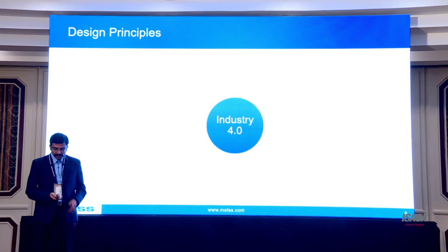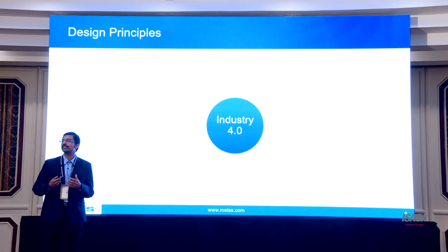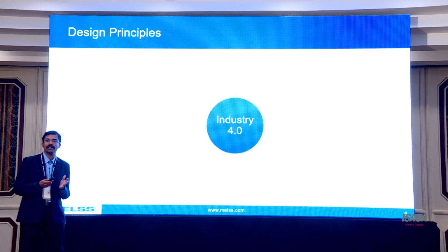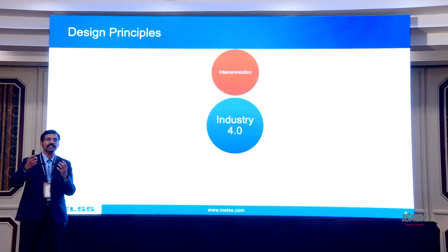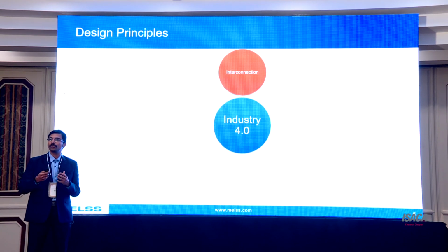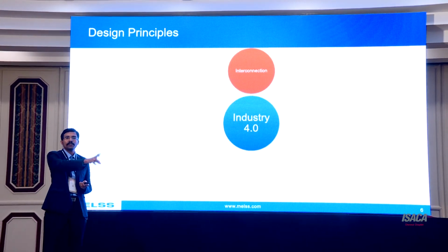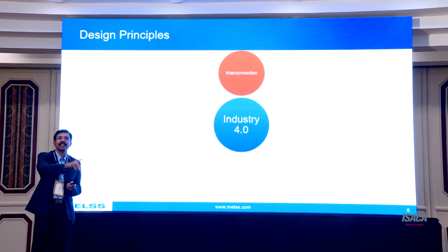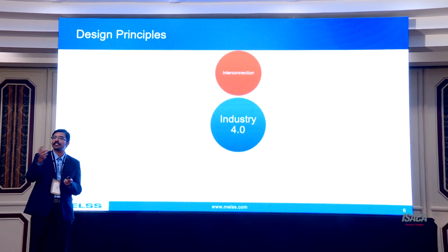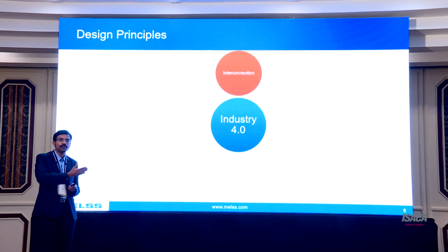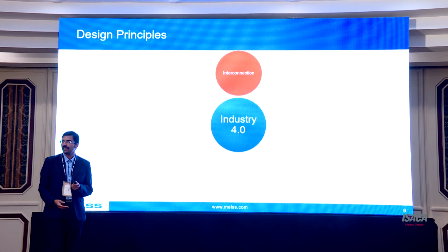So the basic principles of Industry 4.0. So how do you conceptualize it, right? It is built on, I would say, four main principles. That's what it's arrived at. So the first one being interconnection. So you want to have interconnection between devices, sensors, computers, and people, right? So different equipment must be able to communicate with each other. So you don't have to say, okay, has machine A completed something, now machine B starts based on that. Rather, we allow the machines to communicate between themselves. If one finds a fault, it can pass this information on to the next.